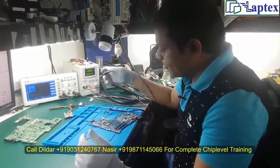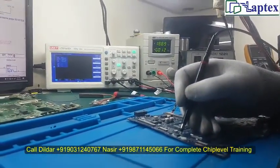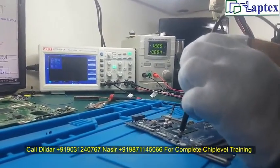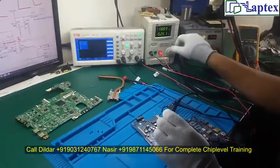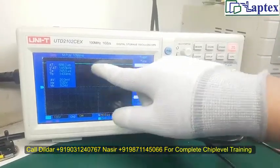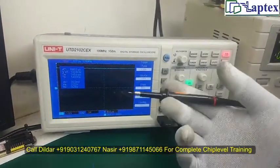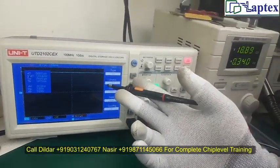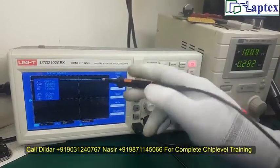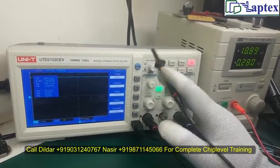So let me turn it on and let me demonstrate what we get on the pin number 7. Now I am holding my probe on the pin number 7, and let me turn it on, and you will see the 3.3 volt without glitch on your DSO. Since we are having the capture mode here, even if you are not checking it in capture mode, you will get a straight DC line on your DSO. So this is the indication that it is perfect, quite fine, there is no problem at all.